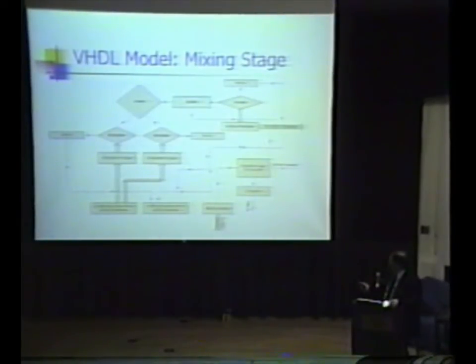It starts coming from the ADC interface, getting multiplied by gains, and added together, which is the mixing process, into a buffer. It is then divided out, determined by another gain used as the master gain, and sent back out to the ADC interface. A counter with a 50 megahertz clock was used to generate the control logic for all of this, and a signal out to the ADC interface to know when to read the signal.